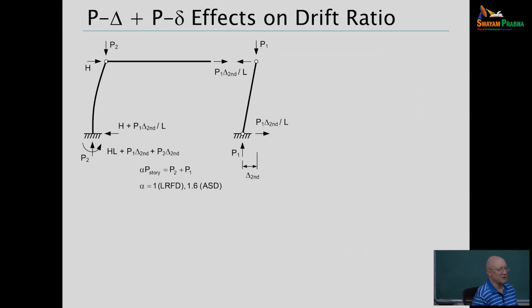Now let's suppose we've got some gravity load also on the lateral load resisting system. The leaning column on the right here is just a surrogate for a whole bunch of gravity framing that's just columns that aren't providing any stability or any resistance to load themselves, but are carrying vertical load to the foundation. So I've got my one column here on the right that's representing that. And then the cantilever is representing whatever is providing my story sidesway stiffness.